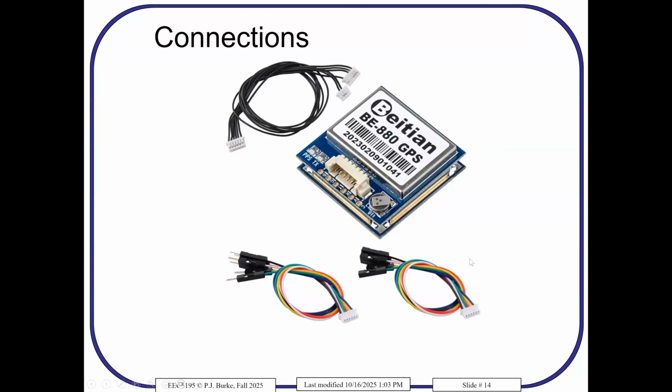And here's the wiring. Good news, no soldering needed because it comes with this connector. And this is called a JST. You can also crimp those, believe it or not. And you can depin them and move them around, but that's really hard to crimp. And with this particular GPS model, it should have all these, and this is a DuPont. Now they're 1x1s.